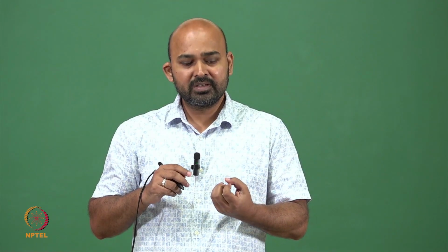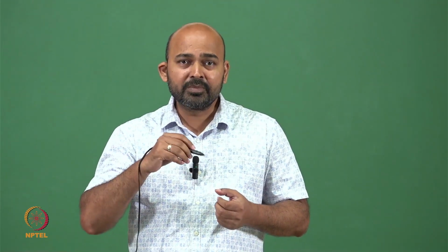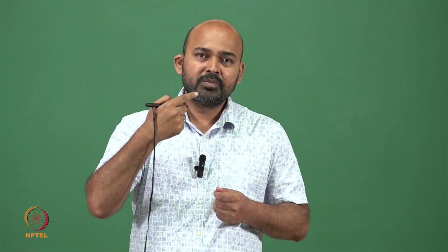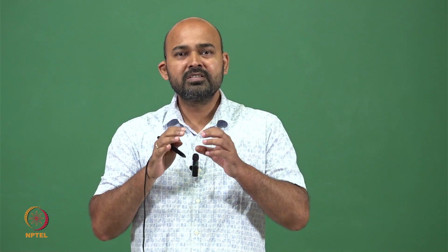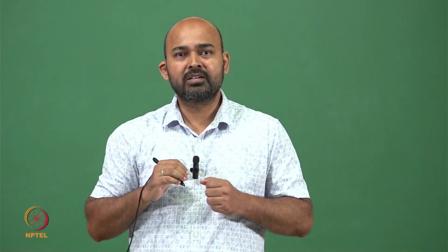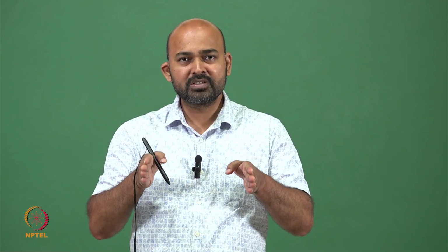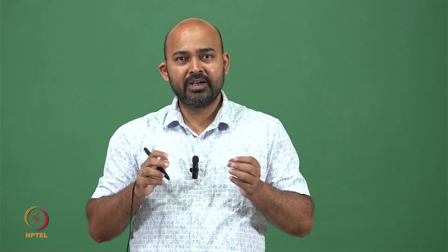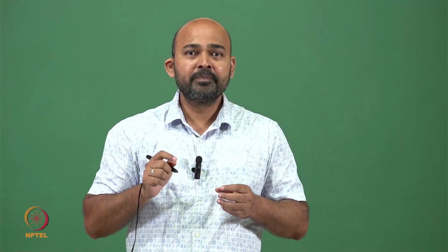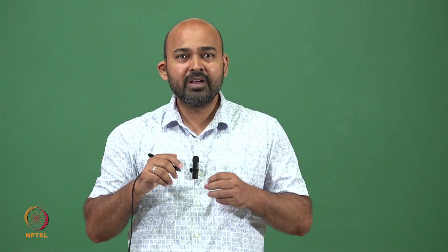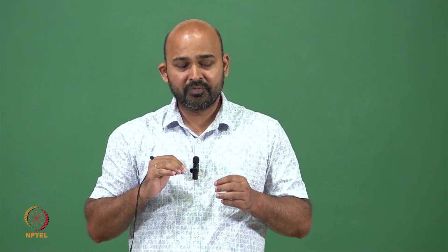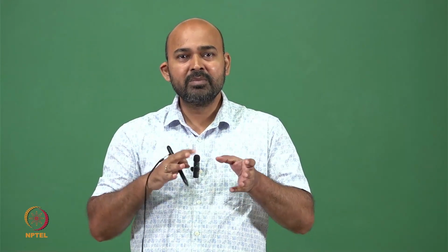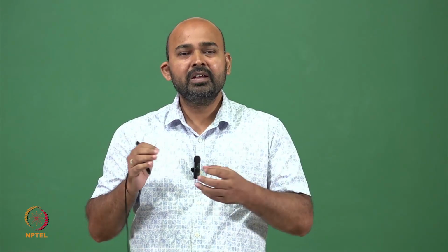If an electron achieves this much energy, it can jump from the valence to the conduction band, and when the electron goes into the conduction band, it is now available for electrical conduction. If we apply an electric potential across the semiconductor, then this electron can move and provide current. However, if the electron does not receive enough energy, of the order of 1 electron volt, all these electrons stay in the valence band.